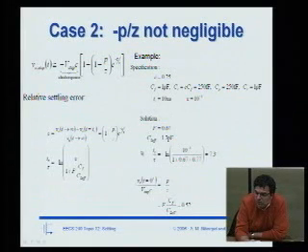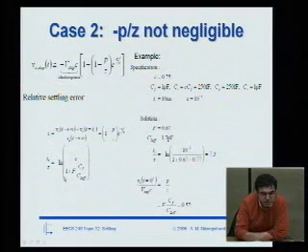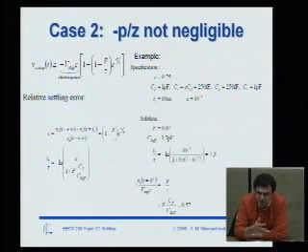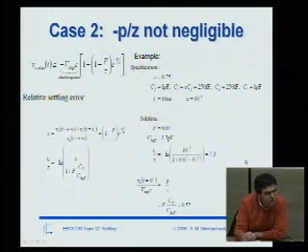And so running the numbers here, you can see that because P over Z is a factor of 1/2, if I plug that into here, it's going to make a big difference. It's actually going to change the settling time. If you neglected the effect of the zero, you would actually end up designing an amplifier that were too slow. So we have to speed up the amplifier a little bit to compensate for that zero. But it's not very difficult to take that into account. Okay, questions?